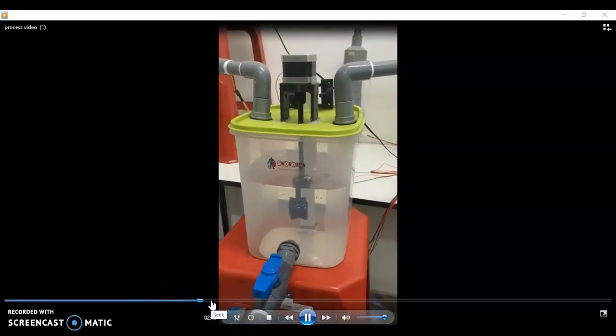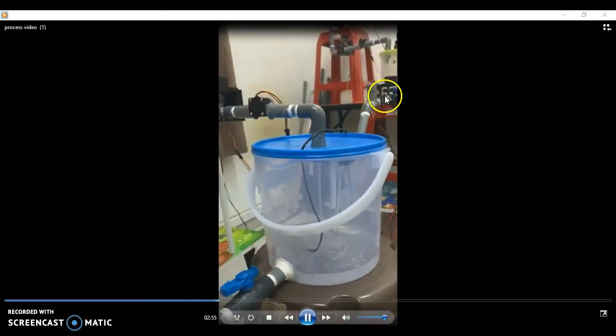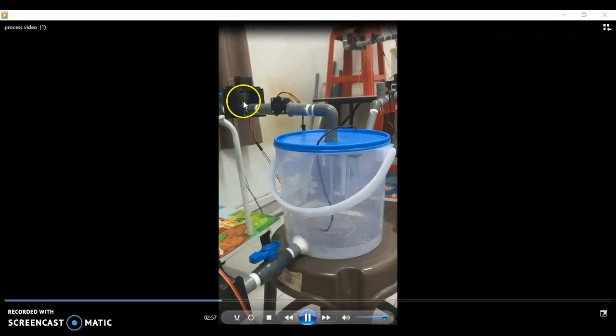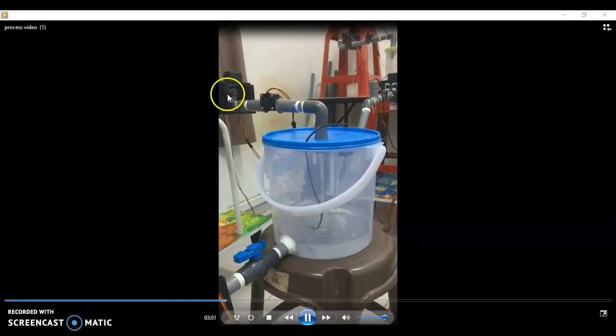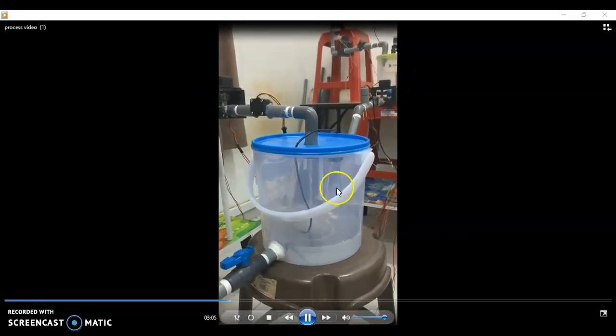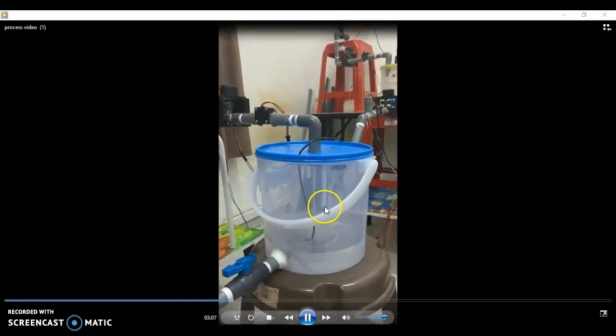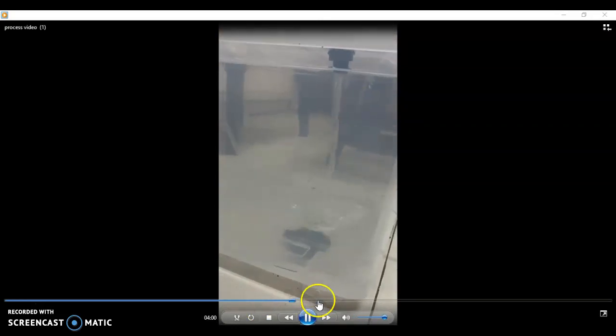After the reactor is filled, the output valve will be opened, and also another valve from a mixer over here, which has cooling water that will be mixed with the product from the reactor. Both of them will fill up the mixer until a certain level. After the level is reached, the output or product valve will be opened.